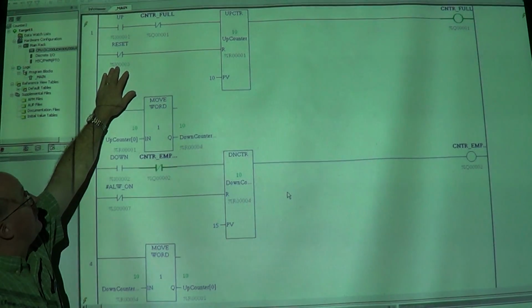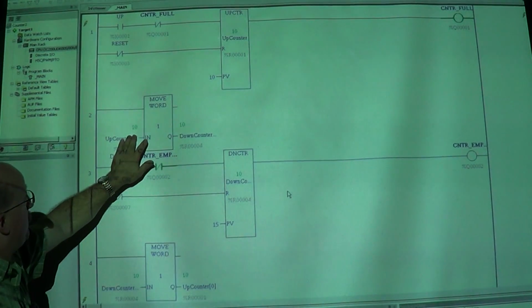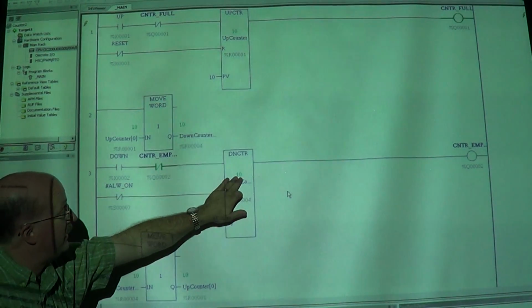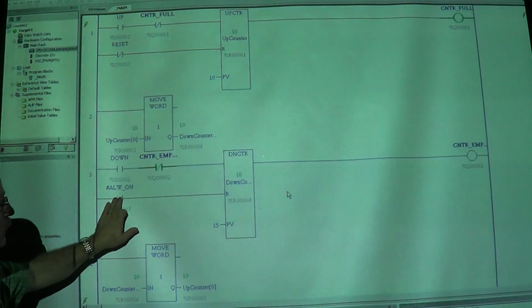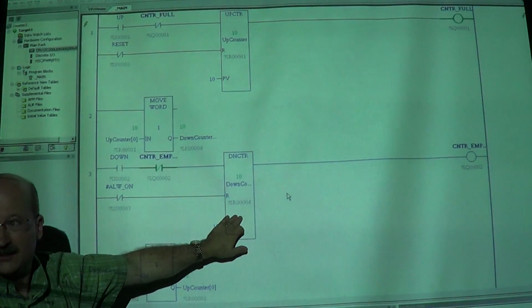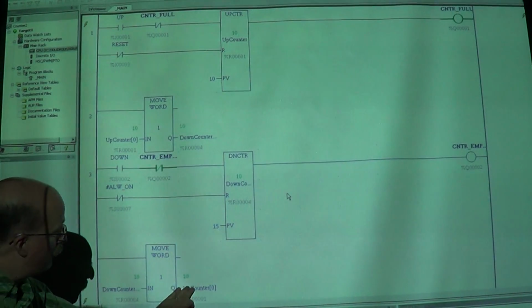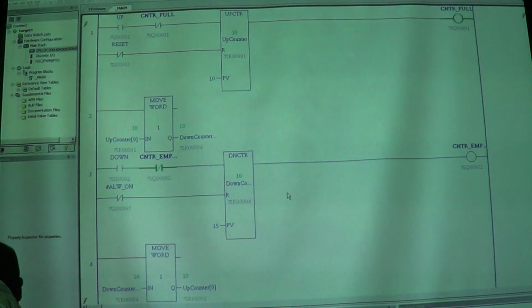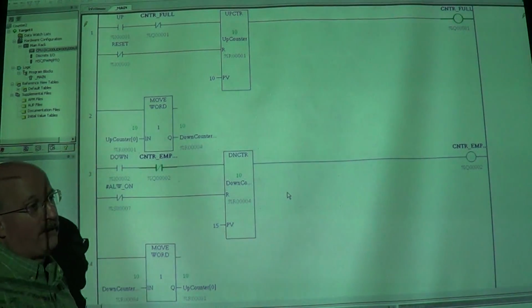Okay? I had to move that reset off here because tell me what happens. I push my reset button, that goes true, resets this to 0, correct? Okay, comes down here, picks up a 0, moves that 0 into my down counter, right? It'll come over here. If that was the reset, that reset would be on, right? Reset this, and what would the down counter reset to? 15. It'll pick up the 15 and move it in the up counter. My up counter will be set to 15. Okay? So in the case of an up counter or down counter, a reset input will clear off the counters. You only do it on the up counter.